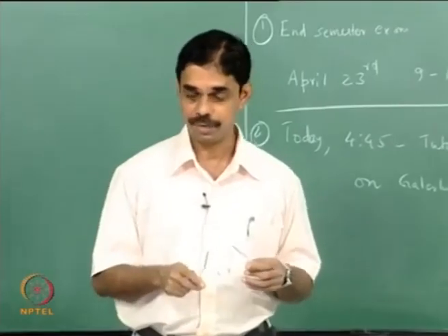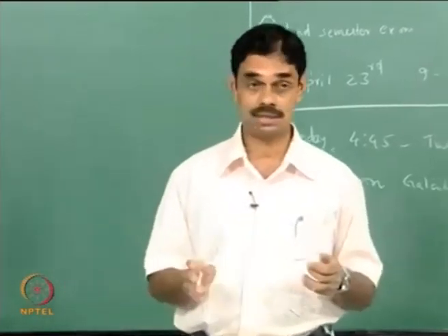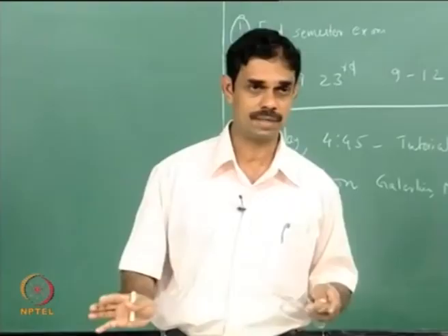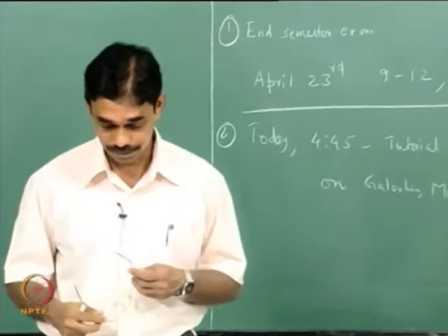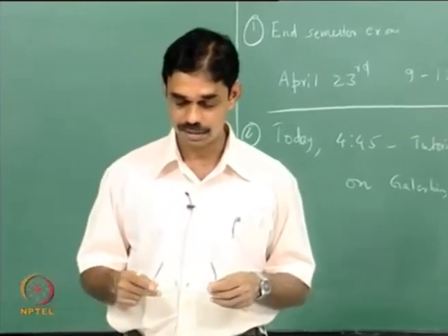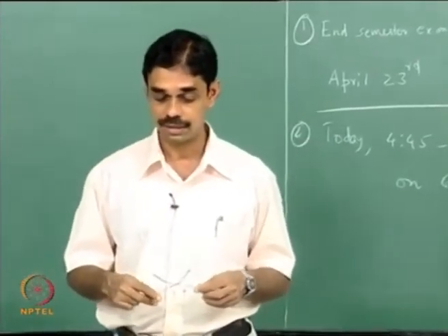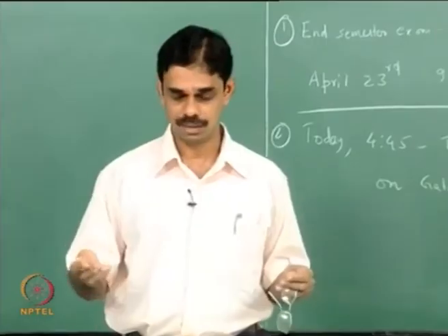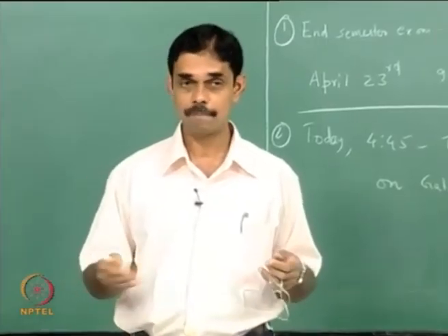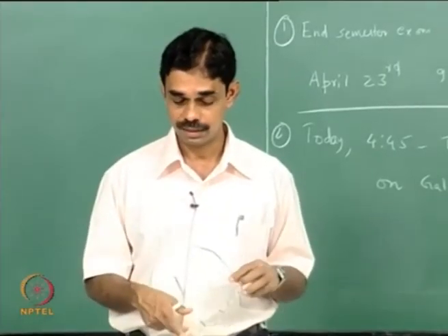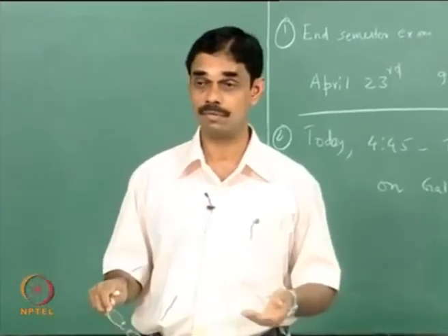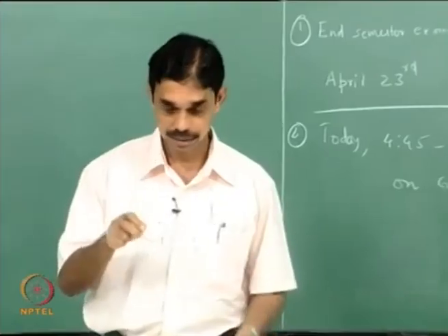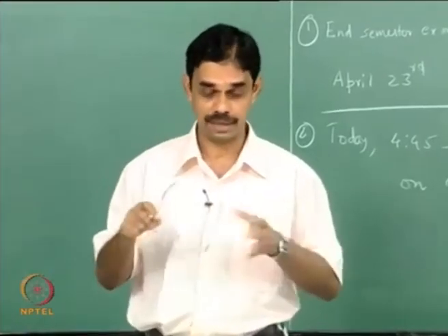Everything is the same, we have feedback between acoustic waves and heat release, and that is what makes the instability. There is no difference in that, the only difference is how the perturbation heat release is coming. So acoustic perturbation of velocity or pressure at the fuel injector, usually acoustic pressure at the fuel injector, will fluctuate, and that will modulate the fuel concentration, and the velocity fluctuations will also modulate the airflow rate.